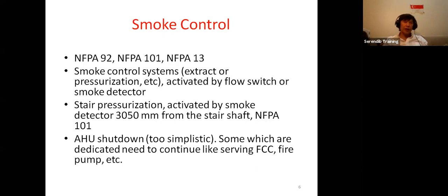Okay, so basically, as a designer, the fire alarm guy needs to know. He's an electrical guy, so he needs to speak to the mechanical guy and ask, "Are you going to provide a staircase pressurization system?" If the answer is no, you go away. If the answer is yes, immediately you need to place a smoke detector not more than 3 meters from the door of the staircase. Then you develop your other spacing from that onwards. And the mechanical guy needs to speak to the architect to find out, is this a high rise or is this a low rise? If it's a high rise building, then the pressurization system becomes mandatory.